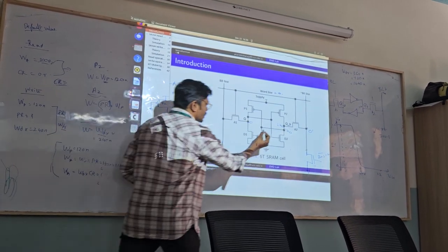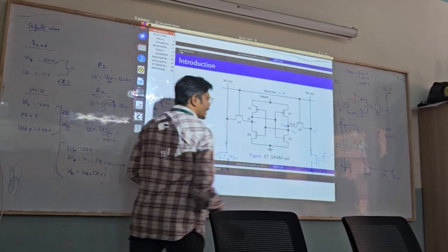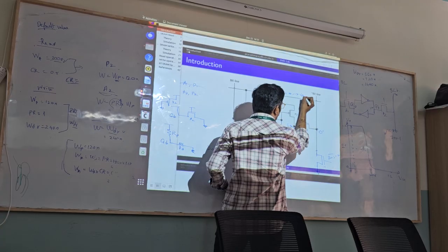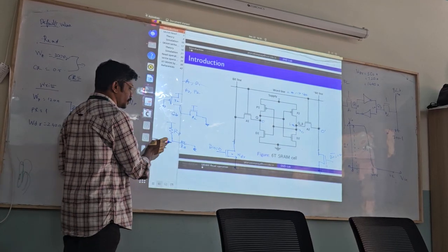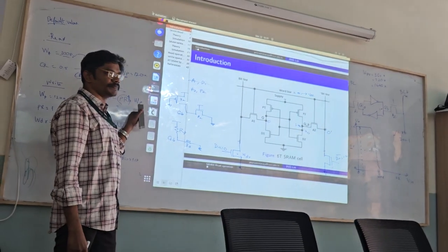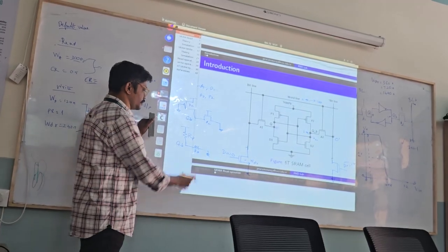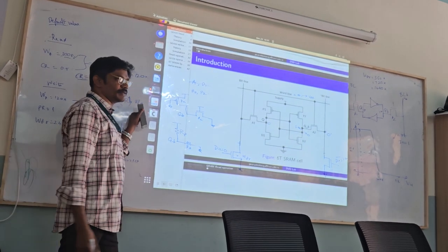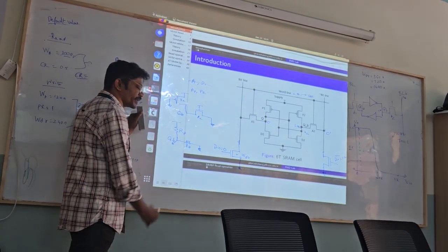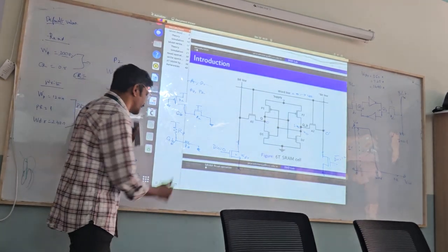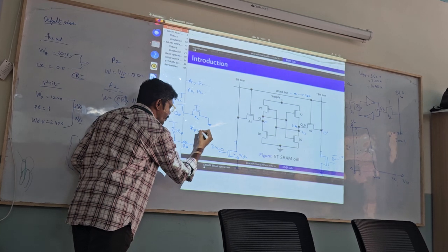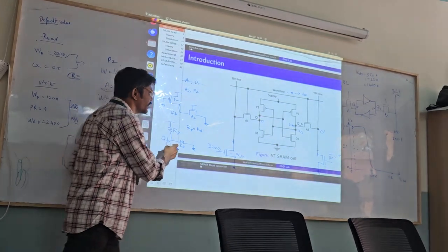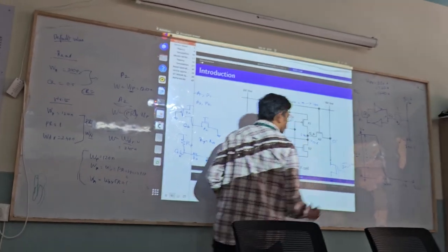Initially, we know that this value of Q bar is at 1.2. The moment I switch this word line from 0 to VDD or 1.2 volt, what happens to this Q or Q bar? What change in voltage will we have? And assume that RP equals RA. 0.6, right? So in this case, from 1.2, it goes all the way to 0.6.